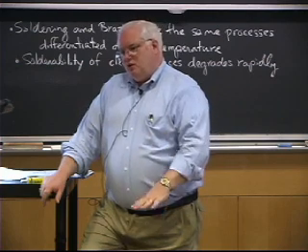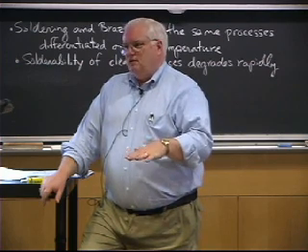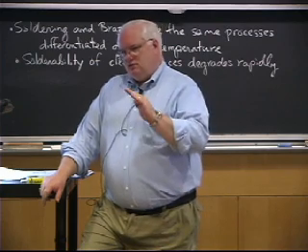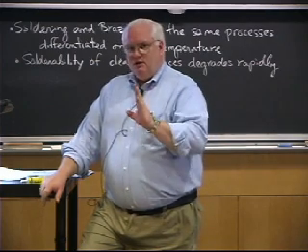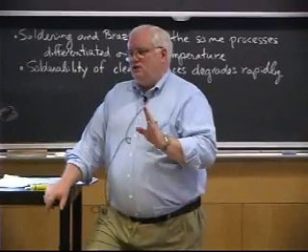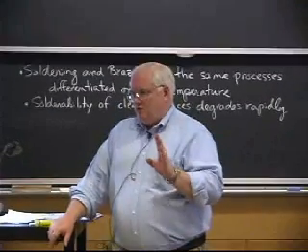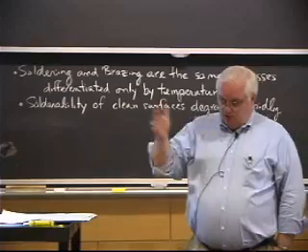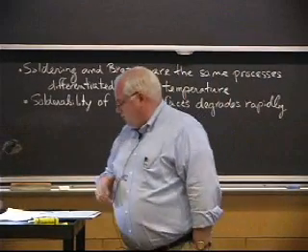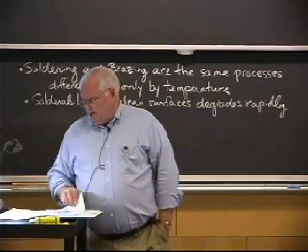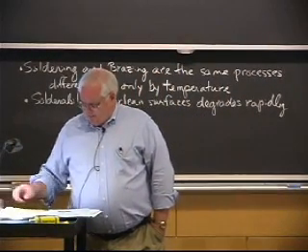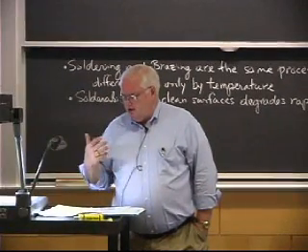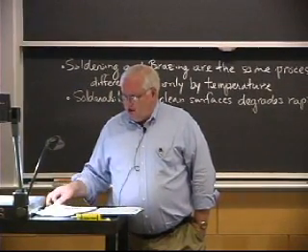Well, the oxide actually grows over several minutes, and in 10 or 15 minutes, it reaches not a final state, but it will have grown significantly over that period of time. I showed you a little curve of some of that people have measured over time. But it continues to grow, and we're going to talk a little bit more about cleaning today so far as that goes. And then we talked about how you have to have spreadability and thermal stability, and finally got to